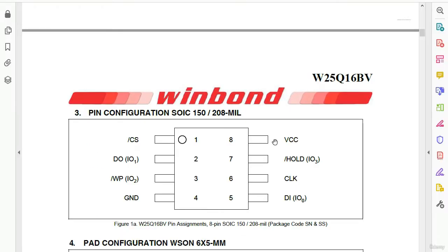When you plug the adapter into the power jack of the laptop motherboard, you should go directly to the BIOS and you should find 3.3 volts in pin number 8 without powering on the laptop. Okay, so this is the pin configuration.